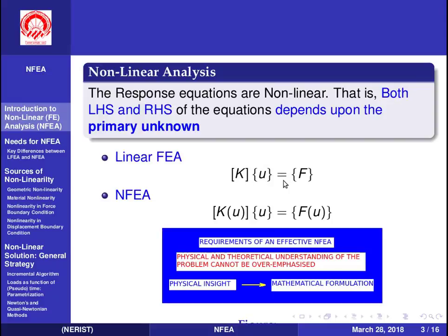linear problem. On the other hand, in a nonlinear problem, this stiffness matrix will be a function of the unknown displacement U, and similarly the force vector at a given stage of solution will depend on the unknown displacement vector U, and that's why we need to apply nonlinear equation fundamentals to solve this kind of equation. So that is what nonlinear finite element analysis is.